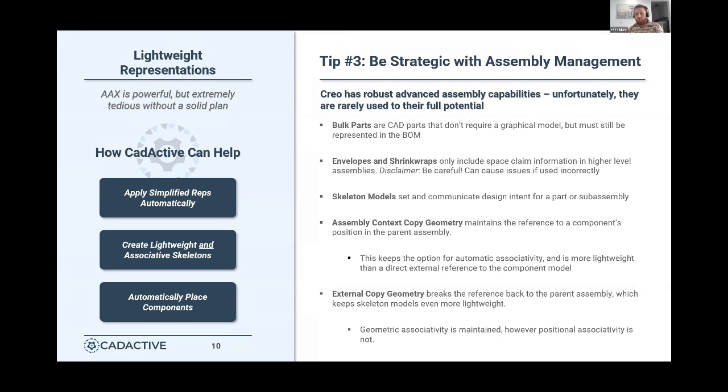First, I'll mention bulk parts. They're a great way to lighten the weight of your model. For instance, maybe we know that this standard piece of equipment has these 4 lag bolts and nuts and washers. So why would we need to actually model those and show those in our design? Let's just put them in the bill of materials, right? A lot of folks use these for things like paint or sealant or glue, maybe things that aren't one each.